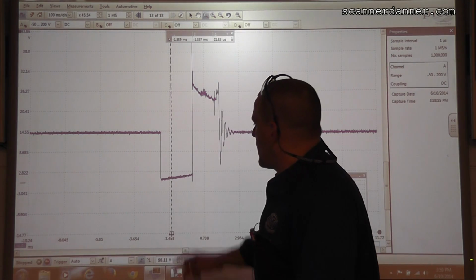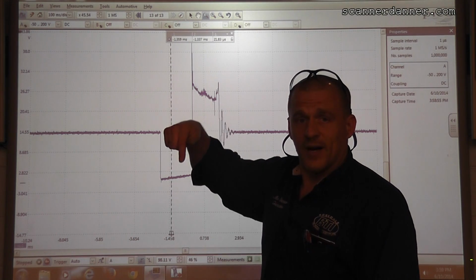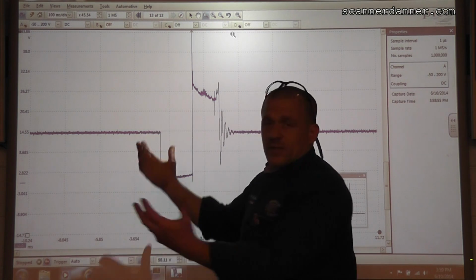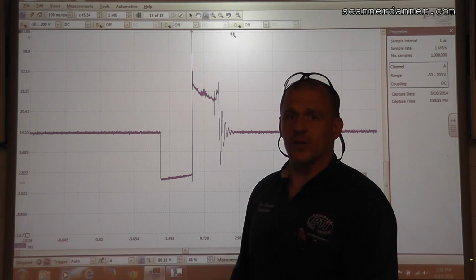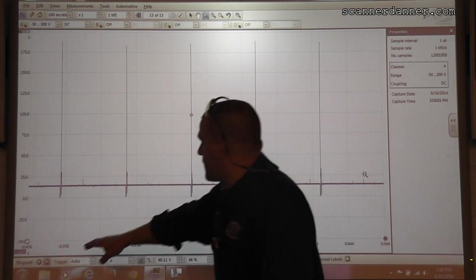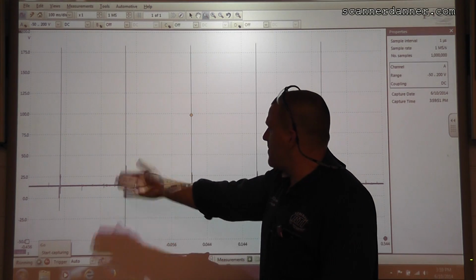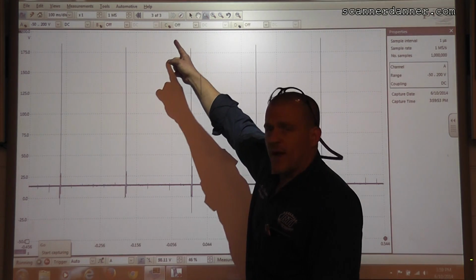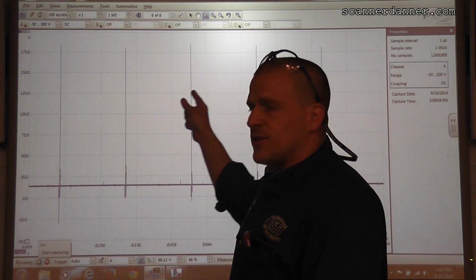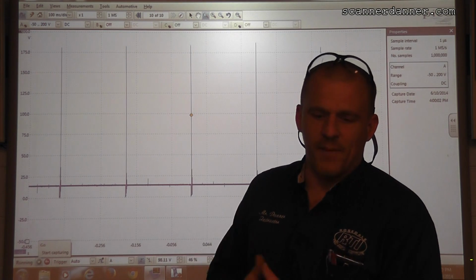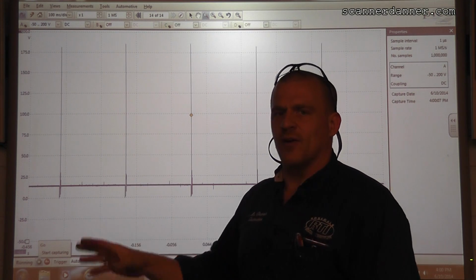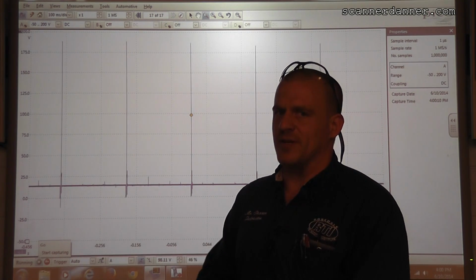The answer is no, and really what that tells me is I could probably drop my sample rate down a little bit if I wanted to. You might be thinking, why would you want to? Well, if I want more than 32 frames on this time base, I have the ability to lower my sample rate and change my default maximum number of waveforms in that buffer. So when we do that though, do we need to consider our detail? The answer is yes. We still need to have our detail.